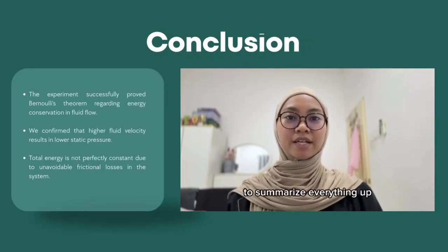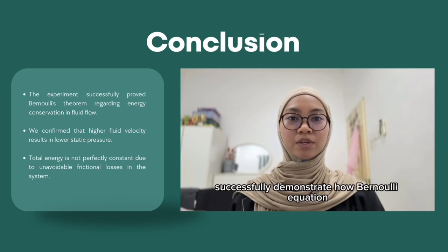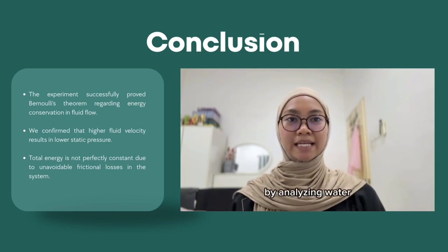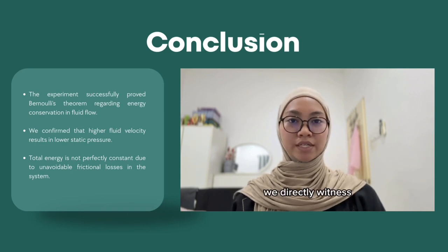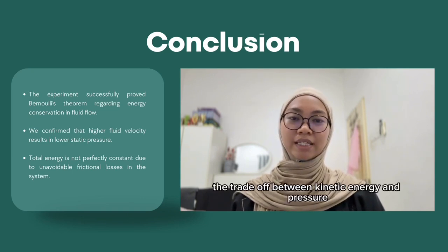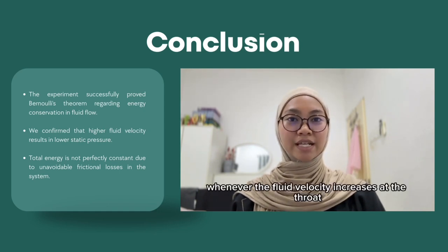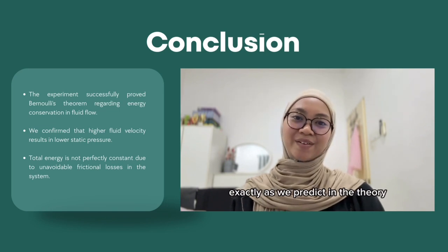To summarize everything, this lab successfully demonstrates how Bernoulli equation governs real-world fluid dynamics. By analyzing water flowing through our venturi apparatus, we directly witness the trade-off between kinetic energy and pressure. Whenever the fluid velocity increases at the throat, the static pressure drops exactly as we predict in the theory.